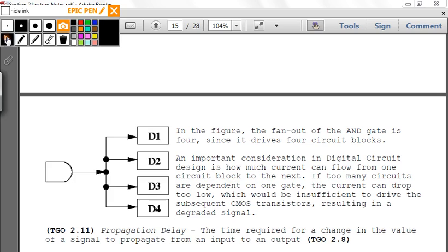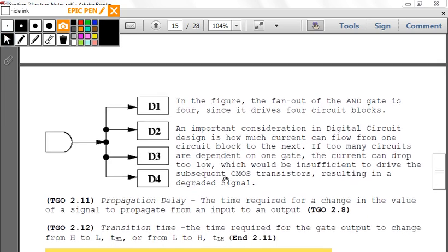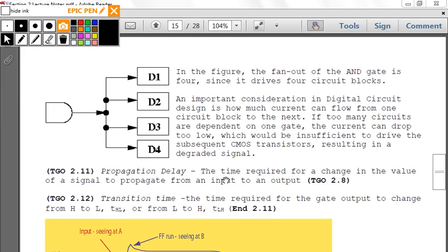Is there anything that prevents too much fan out? Oh yes, fan in and fan out. Basically, it'll do calculations based on a predictive technology that's used within the embedded system compiler. Based on that, it'll see whether or not you can successfully drive the gate. So this is design automation, which is another whole field of testing, fault tolerance and design automation. There are people for whom this is their job. This is what they do for a living.